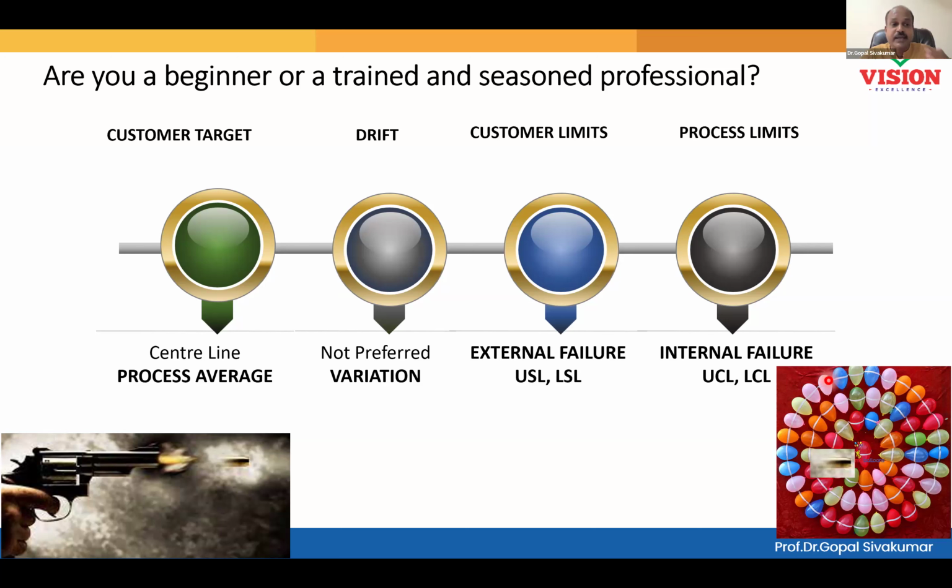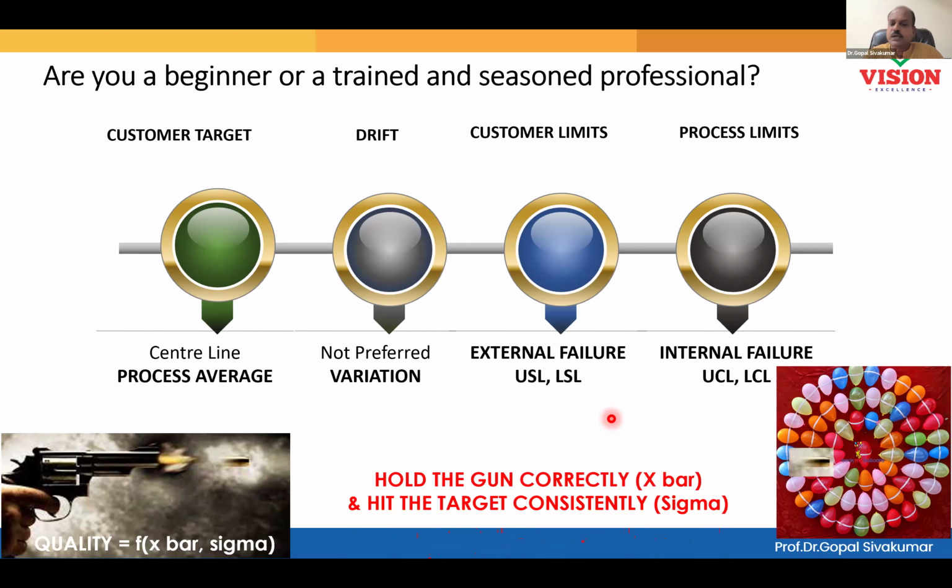So that is why any observation beyond the control limit should be called an out of control scenario. In a control chart, that's what we are doing, isn't it? Every time a point appears outside the control limit, we immediately intervene and stop the process. So I want all of you to understand that and maintain the same thing on your shop floor also.